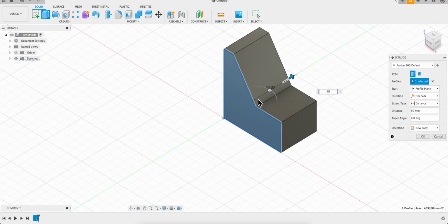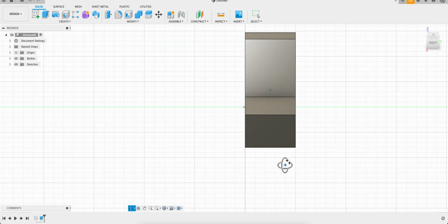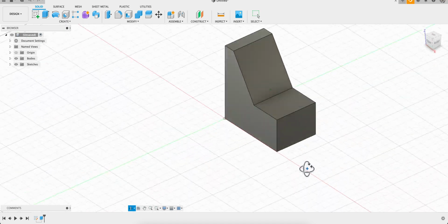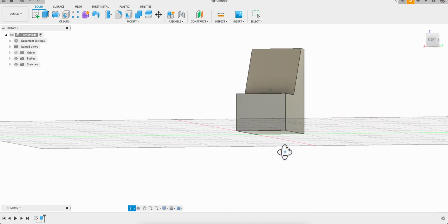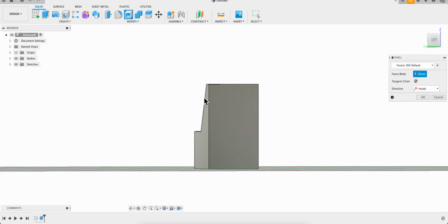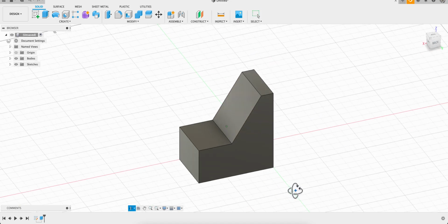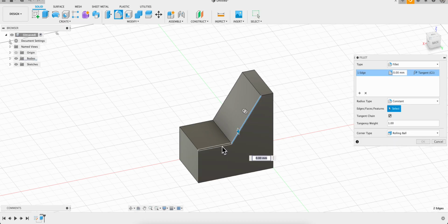As I mentioned, we just wanted to create a kid's look of the mold. So right now we have the chair, it looks something like this, but we don't want to waste too much material on it, so we can shell it. But again, before I shell it, I need to fillet the sides to round it to make it look better.